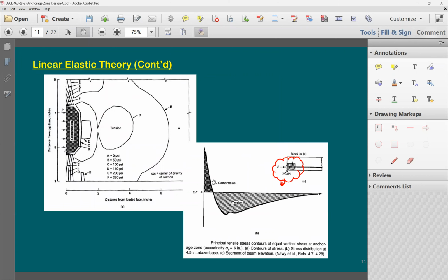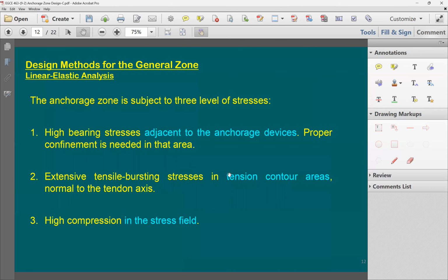You can do the same study in the local zone if you want to. So if the force here is going to be right in the middle, you can just take the block on the same beam, and let's say here's a beam, let's say 9 units. I can just go here 9 units and study this in the block. But if I'm going to have eccentricity, this can be a kind of local zone. They can study the whole thing again in this local zone.